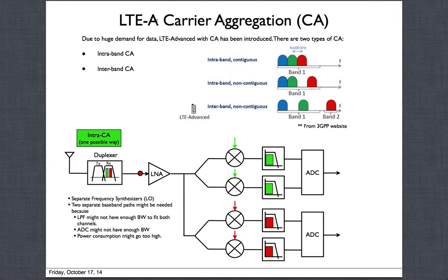So what this basically says is you could have 2 different kinds of carrier aggregation: intraband and interband. But before getting there, let me try to explain what it means. Let's say you are a carrier and you are trying to send your data through a particular channel, and that provides some data rate. Now if you could send 2 channels, don't worry where those 2 channels are, but if you could transmit high-speed data through 2 channels, then that would increase your rate of reception.